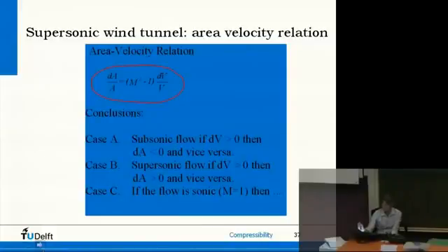Negative. So for subsonic flow, this bit is negative. That means if dA is positive, dV is negative, right? Because plus is minus times minus.